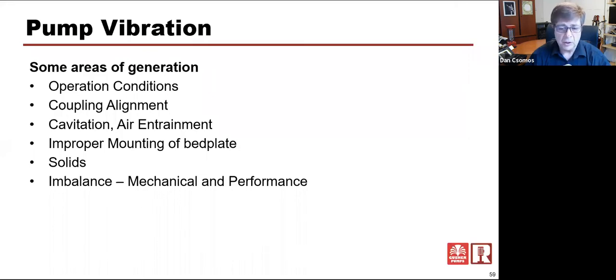And then we get a call a week later or 2 weeks later, and the pump's rattling again. We go back and try to figure this out. Well, it was pumping water-soluble coolant, which is an oil and water mixture, and it's meant for machining operations to be able to cool the machining tips, the drill, or whatever it might be, a machining operation of metal. And it's milky in appearance, so you couldn't see down into the tank to be able to see there was an 18-inch long by 2-inch angle iron.